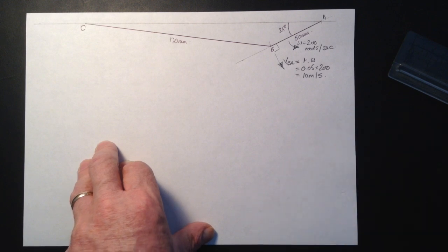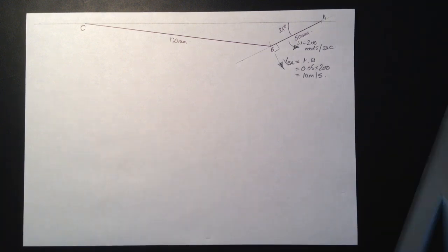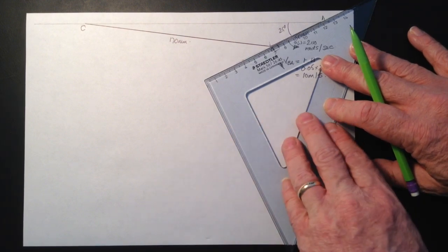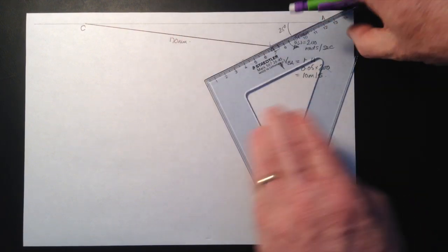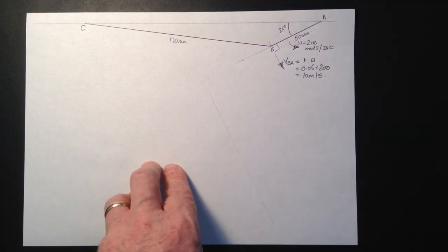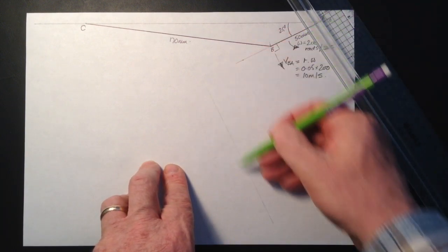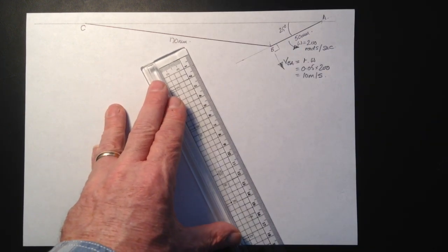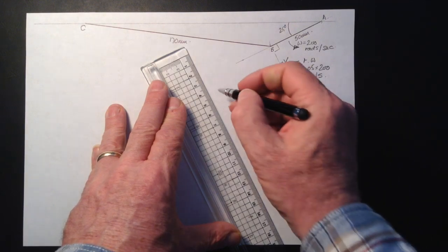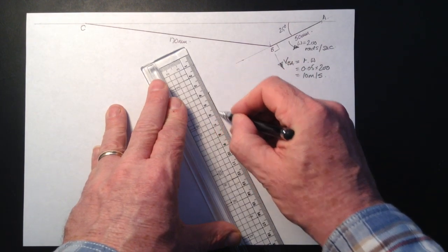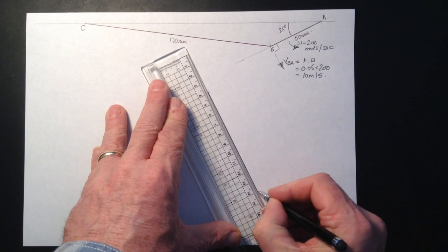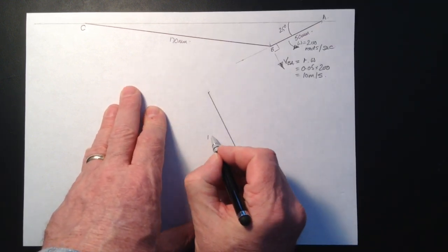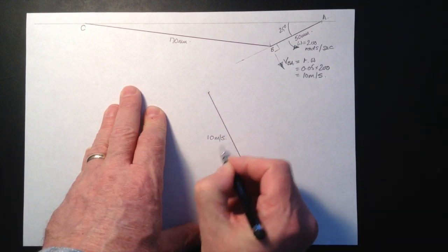So now let's get our first vector down in our velocity diagram. We're going to space it out. We don't have to join it up. We just need to use the directions. So I need a perpendicular to that link. I can put the vector pretty much anywhere on that line. So I'm going to come away from the geometry so I can see what's going on. And I'm going to use a decent scale. I'm going to use pretty much 1 to 1. So I'm going to use 1 centimeter is 1 meter per second. And I can drop my vector in there. So that's the velocity of B relative to A, 10 meters per second.